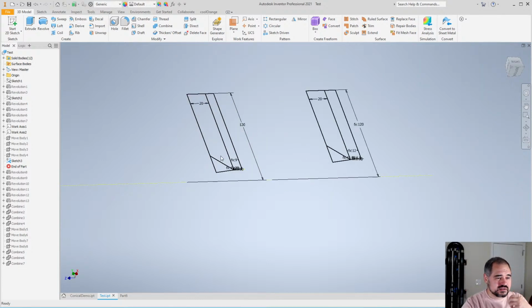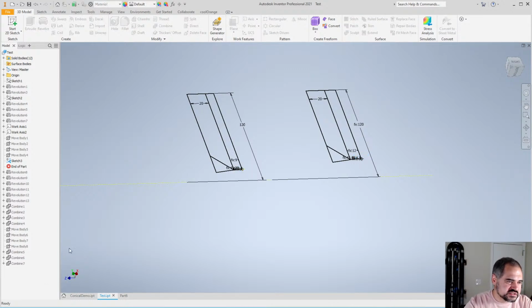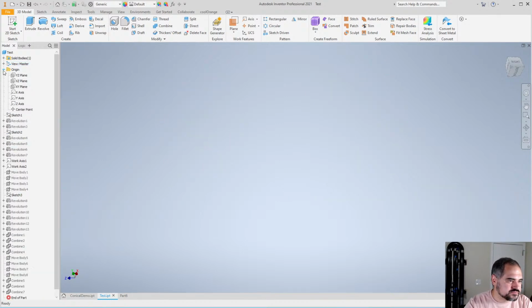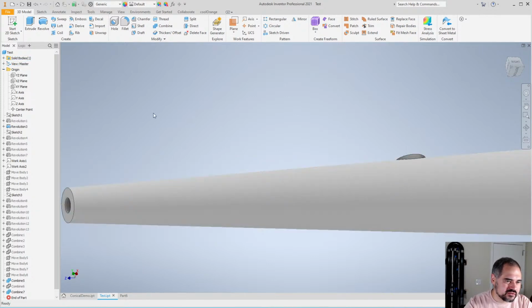If cutting a part by a surface fails, it throws up a vague, nondescript error that you spend 20 minutes searching on how to fix. If cutting a solid by a solid fails, you end up with this weird orphaned piece of the instrument somewhere else that you can just tweak things and get rid of.